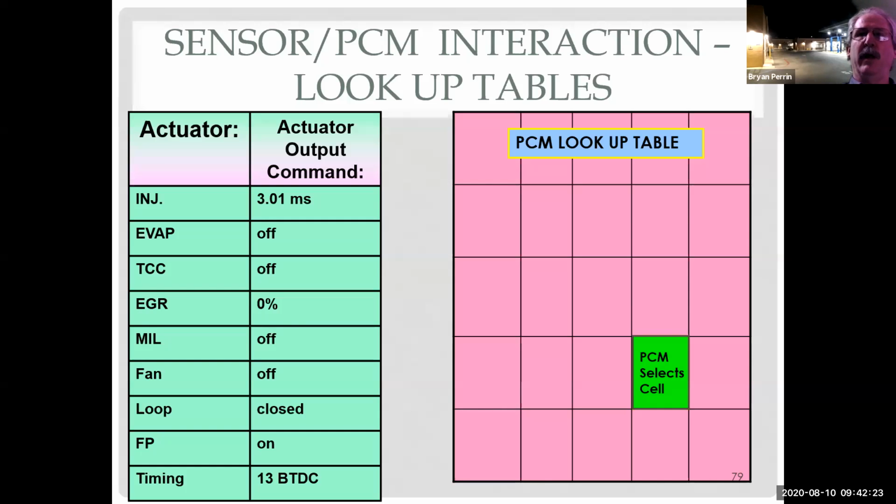I've seen it where the wrong size tires or gear ratio changes cause a car not to run the OBD2 self-diagnostic monitors because we've moved to an incorrect speed and load cell. So these are really important for doing a lot of different things. So if we change something, even as simple as a tire size, it may affect which speed and load cell the computer chooses while we're operating the vehicle.